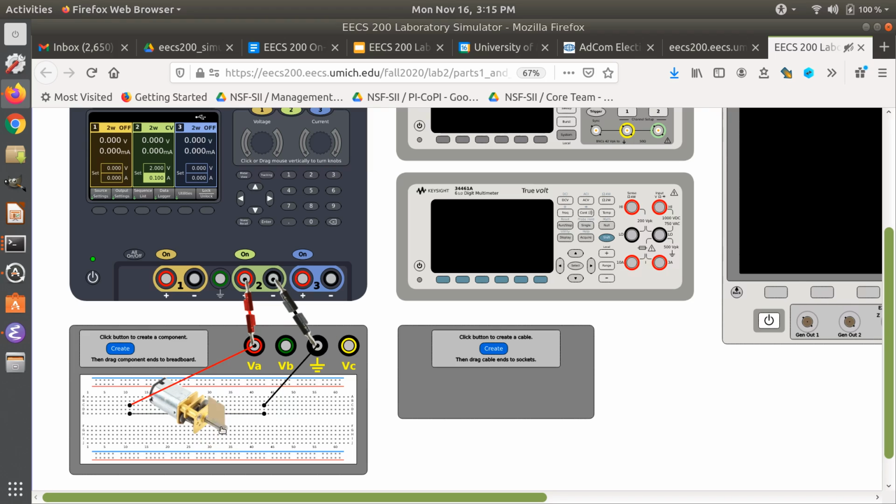Now the other thing you'll notice is the motor here, the flap is moving, it's turning, and the students use that turning of the flap. They count for maybe 10 seconds how many, and they get an estimate of how many revolutions per minute the motor is going. And then they figure out if the input voltage is linear with respect to that output, or non-linear, or some other function. Get a feeling for how that motor works.